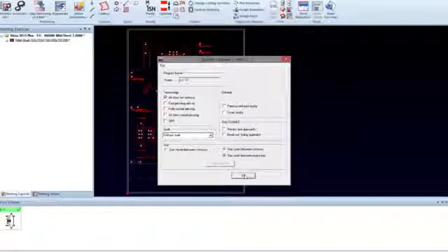Okay, so now we've machined the part and we're saving it to our database. What that's going to do is automatically save that NC file down onto our machine. So the operator doesn't have to go looking for a file, it's already there. If you have Cadman Job installed, which is another application from LVD, this file will already be waiting on the machine. So all the operator has to do is load the sheet up, set his consumables correctly, and press start.